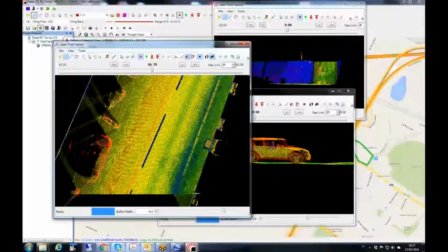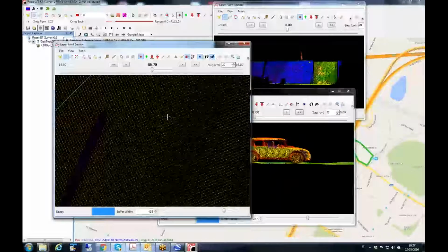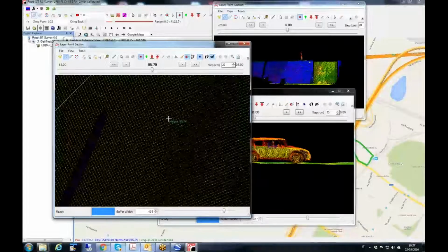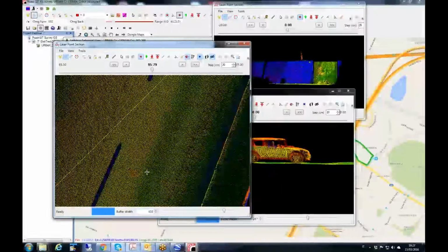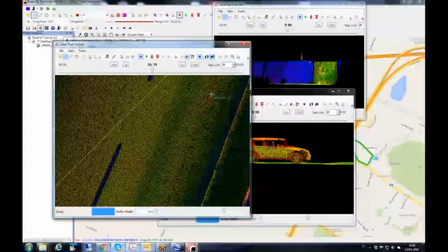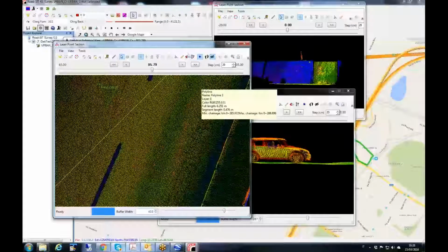When I finish this line, when I finish drawing, the option automatically deselects. This is for security reasons, because normally you will draw in a 3D world, and only sometimes you need to draw in a 2D world. So for security reasons, this option, project onto plane, will disable every time you finish your geometry or every time you shift the command, if you want to change what you need to draw: point, polyline or polygon.